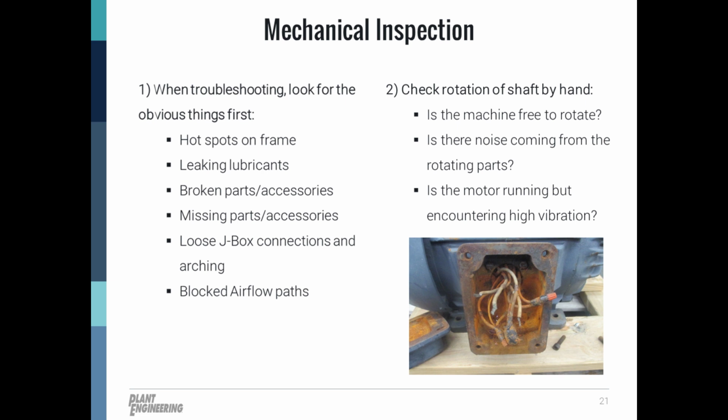But sometimes it's just basic human error of leaving a box too close to the motor, or adding components to a motor to what we think will help with the contamination buildup, but not allowing enough room for air to flow properly past that component.